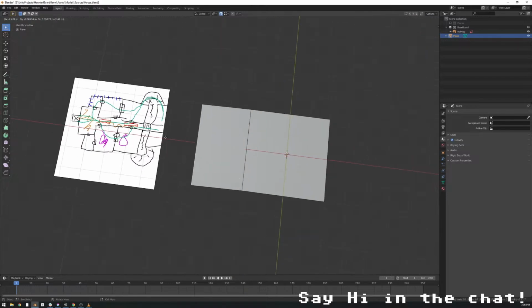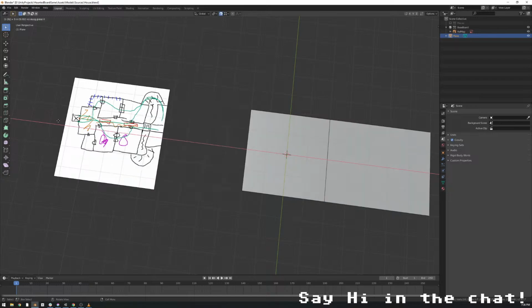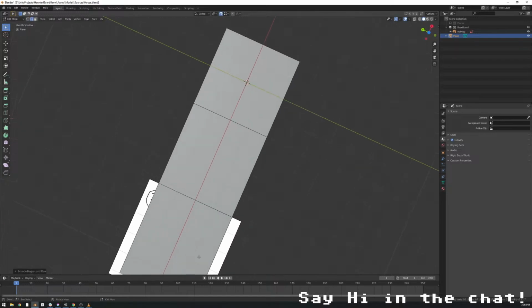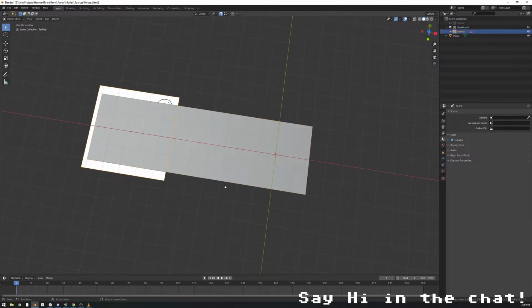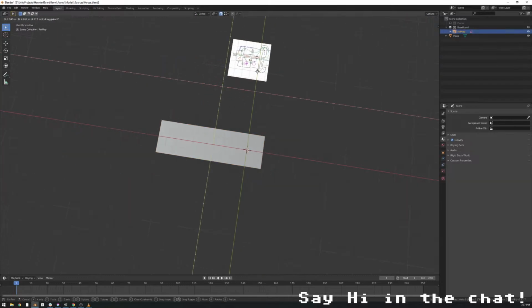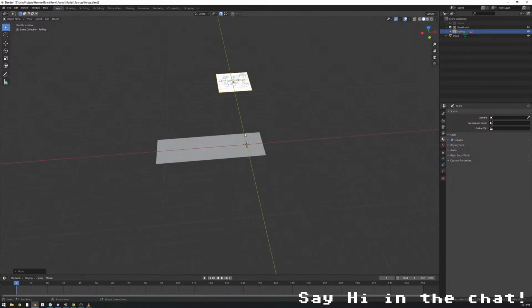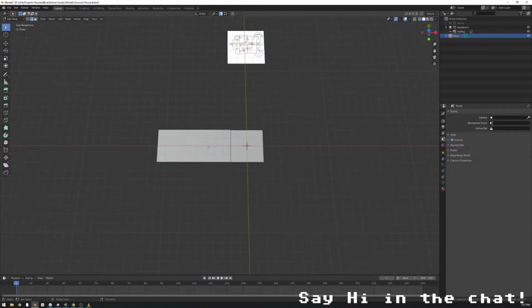So extrude, we're gonna have it be on the X. How big? What's that, about 8? Should we go 9? Odd numbers are fun, right? 8, 9 in the negative. Bam. Gonna need to move our reference. Slide that guy off there. So I'm hitting G to grab it, and then Shift Z to keep it on the Z plane that it's on. Go back into our model.